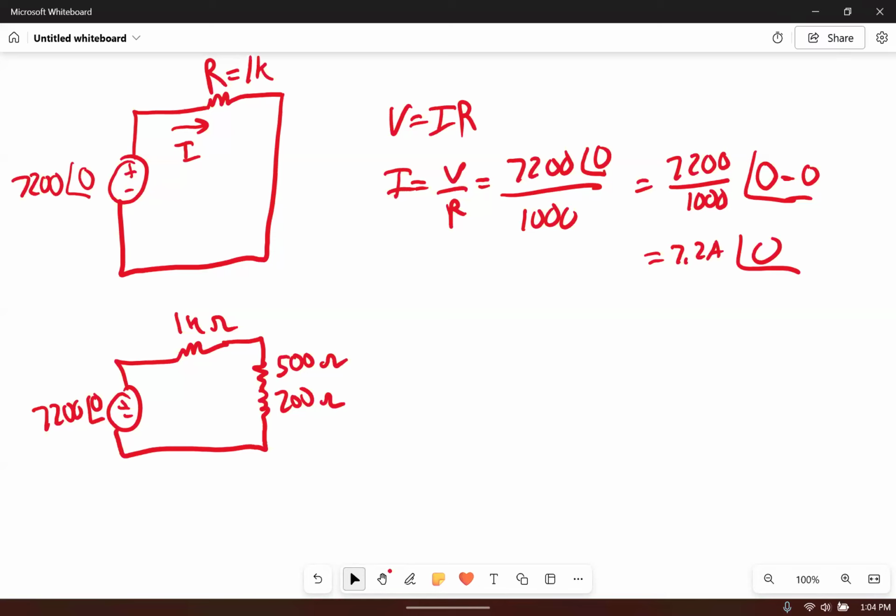0. 0, right? Why is that? What's the job of an inductor? To store energy in the form of magnetic. It creates a magnetic field and it can store energy there, but it doesn't really do that, right? Because you have to have a constantly changing current to get that changing magnetic field. So sometimes it's storing it, sometimes it's discharging it. It's not like a capacitor.